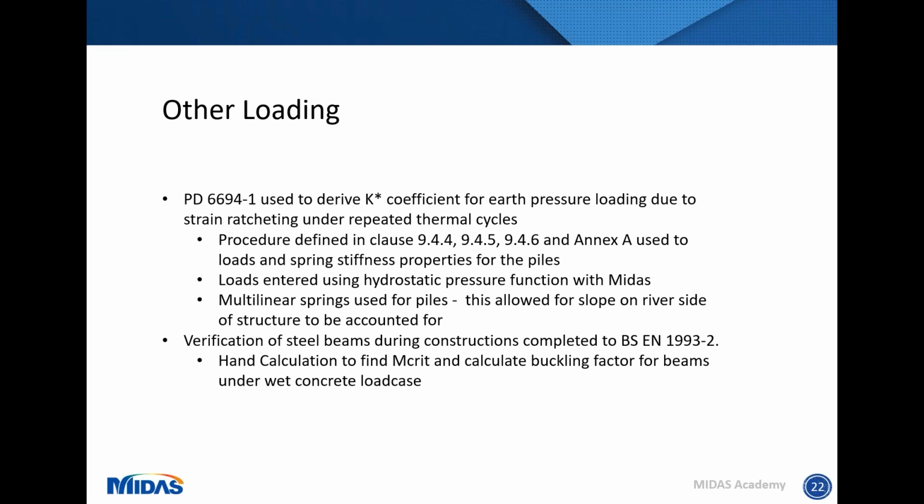This being a structure that is supported on a single row of piles, simply using the coefficients from PD6694 was not quite right. A bit of interaction was required between myself as a structural designer and the geotechnical engineers to come up with appropriate spring values for the piles, and also to an extent for the abutments and the coefficients that were applied for that. So once that was all defined, the loads for K-star were entered as a hydrostatic pressure within Midas,